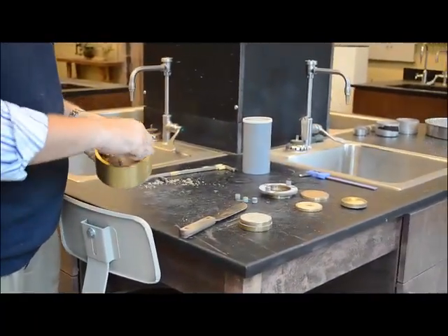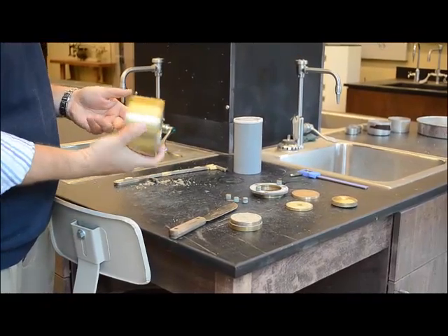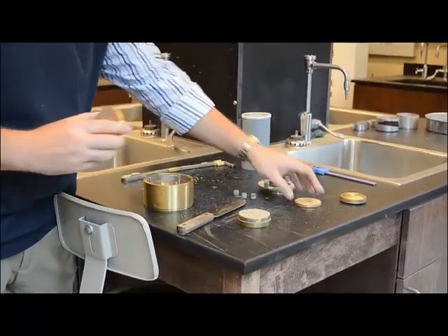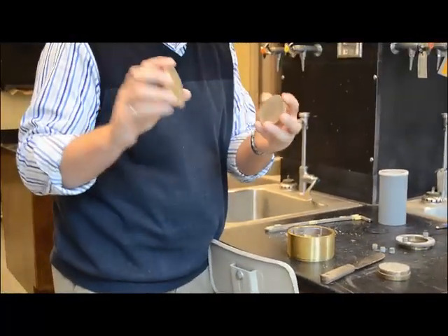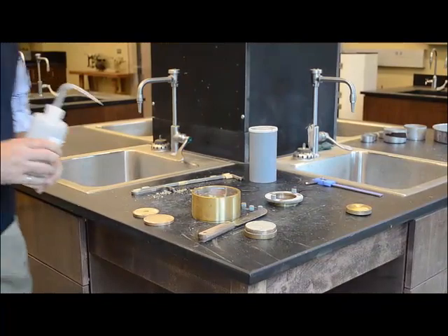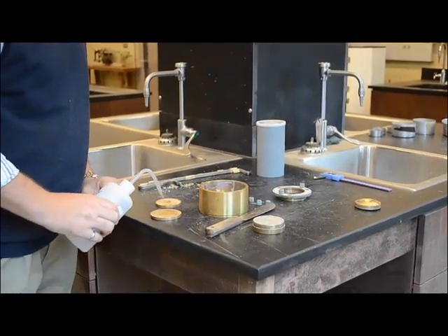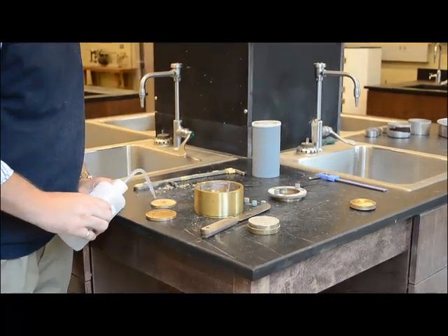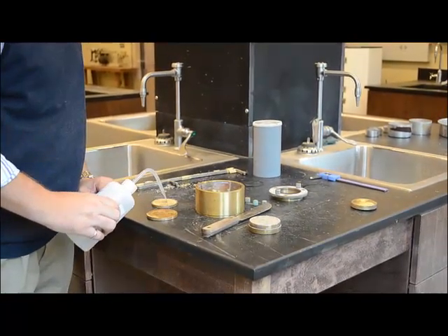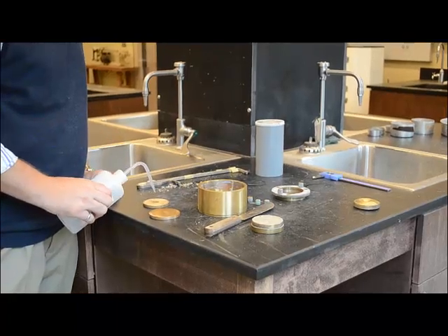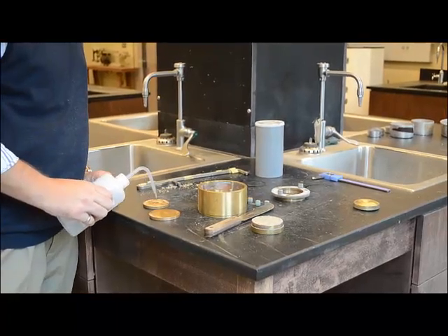Now we have a water bath here, and that water bath is pretty unique. You might have one similar to this or it might be a little bit different, but there are 2 porous stones, one at the bottom and one at the top. We need to make sure that those porous stones are saturated, because the point is we want to make sure this soil sample is saturated completely. So it helps to get water in the top and the bottom porous stone. I did the bottom part.